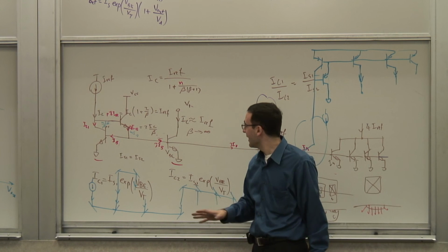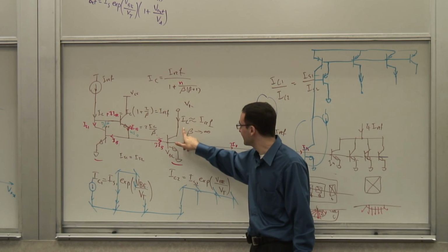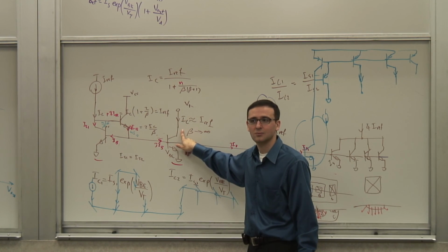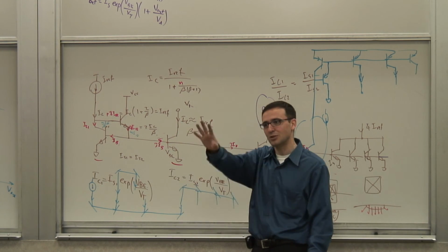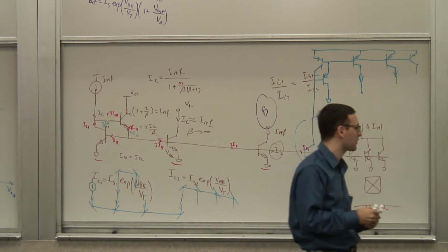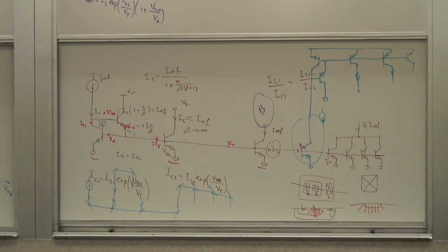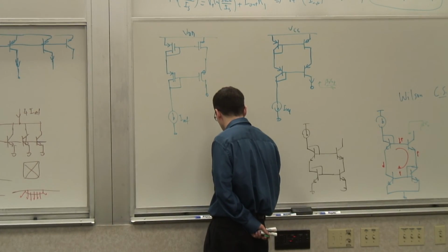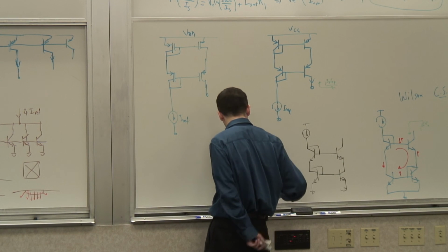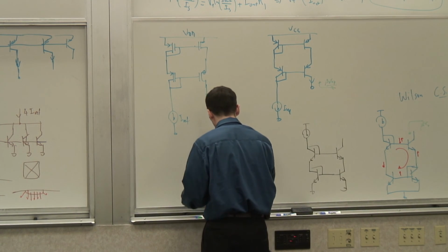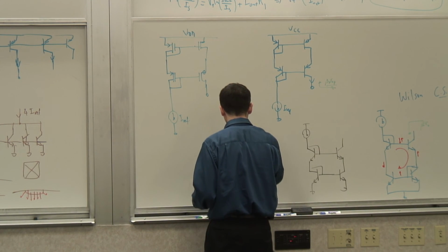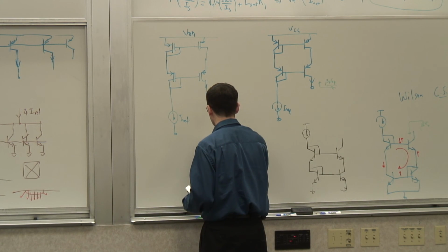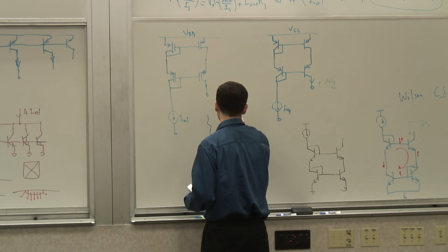But keep in mind, it's not necessarily a good thing to make this constant with temperature or supply. I'll give you one simple reason to think about. If I could make an ideal current source, which doesn't change with temperature, and let's say I have a differential pair or a common emitter, doesn't matter, that's biased with that, and some resistors.